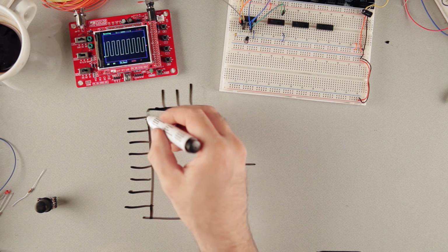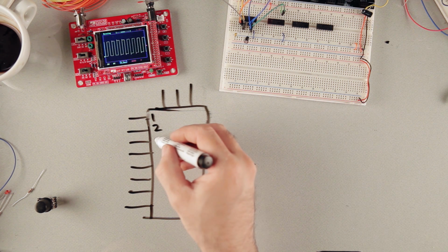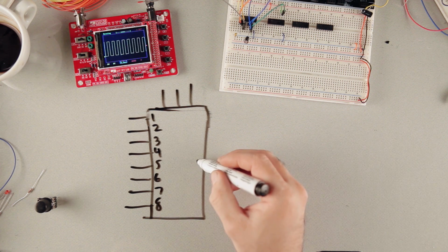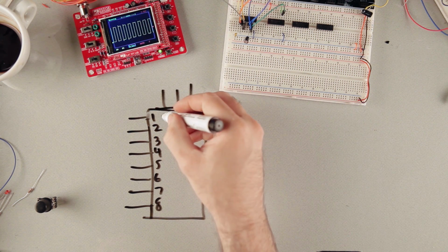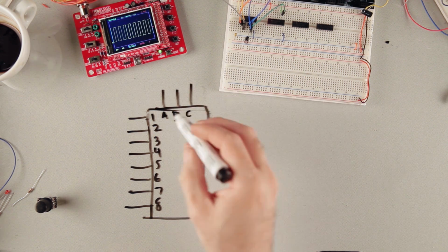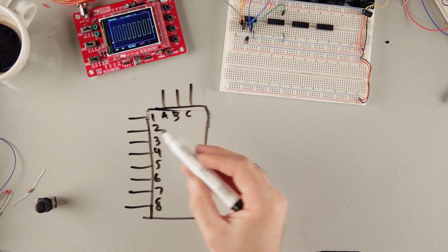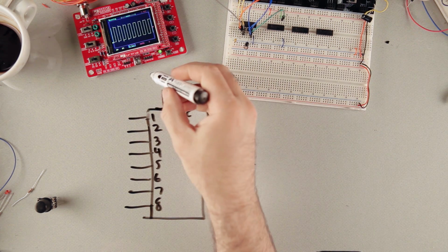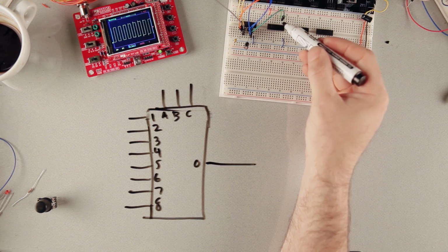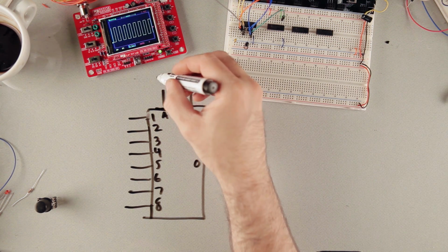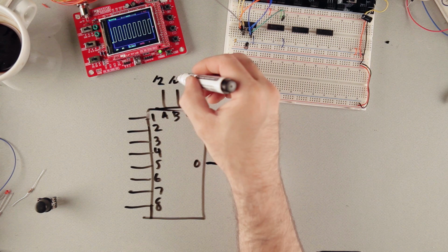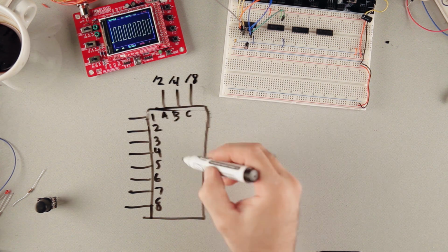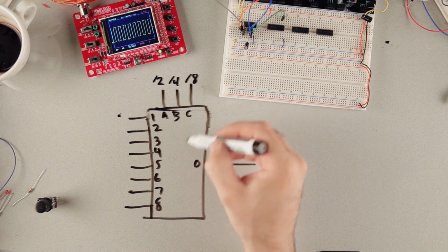Okay, so we've got 8 inputs and 1 output. And then we've got our 3 data pins. And we're going to send logic signals to these data pins. Now, our 4040 divider outputs logic signals. So we're going to connect different pins from there, so we'll say we're going to connect the divide by 2, the divide by 4, and the divide by 8. And what that's going to do is choose which signal to pass through.